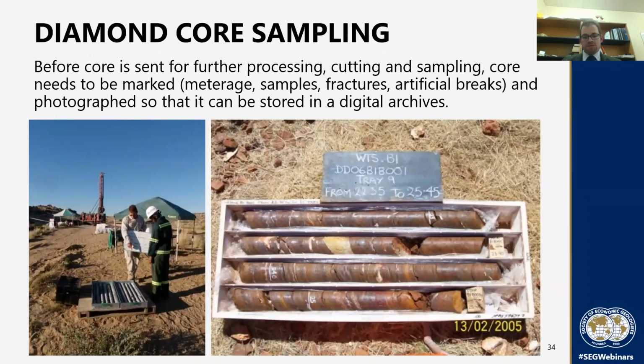Now, people usually do this, but I've also been on sites where this doesn't happen. And it's on these sites, I usually recommended people to quickly implement such processes. And why is it important to take a photo of your core box? Well, in these examples that you can see on the slides, this is fresh, pristine core, and it hasn't been touched at all.